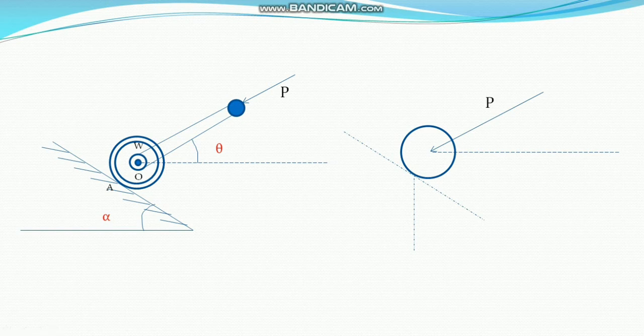Now we have the free body diagram. For the free body diagram we do not need all the other things, only the ruler and the handle line. The ruler has the contact line of the surface, this imaginary line of the surface, which is what you have to draw, and which makes an angle with the vertical line. What will be the angle? You also have to draw a horizontal line. Then the force of application, of magnitude P, is along the handle line. You have to show this. This is very simple.